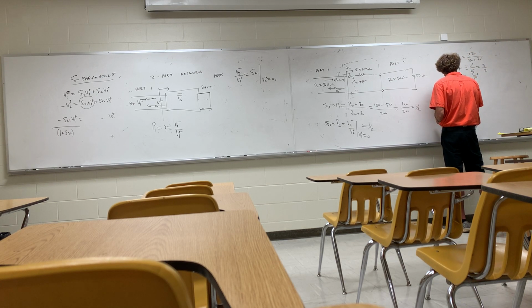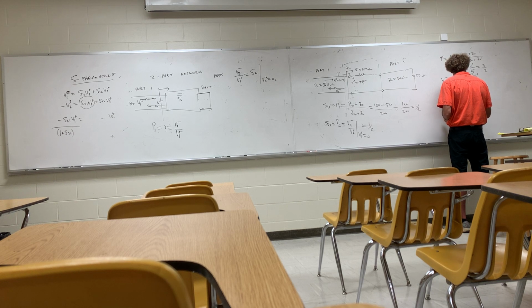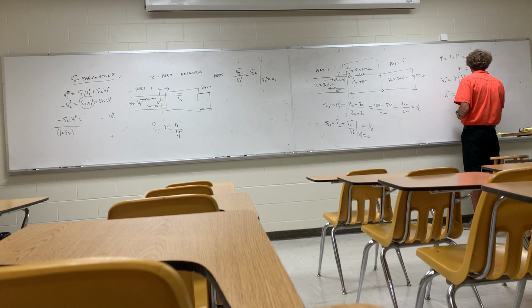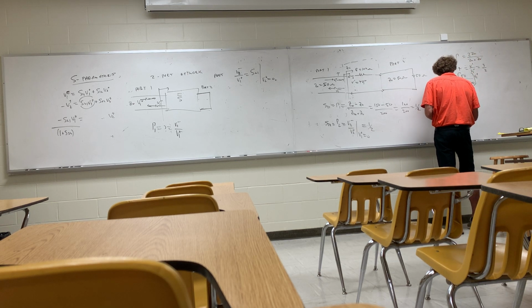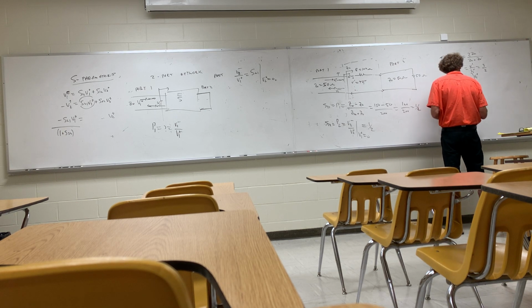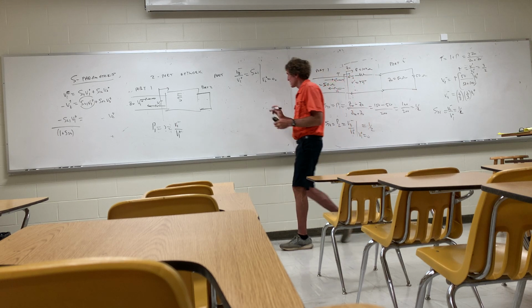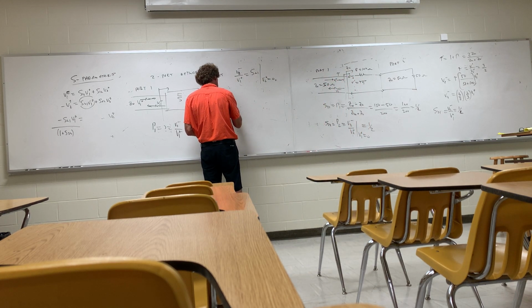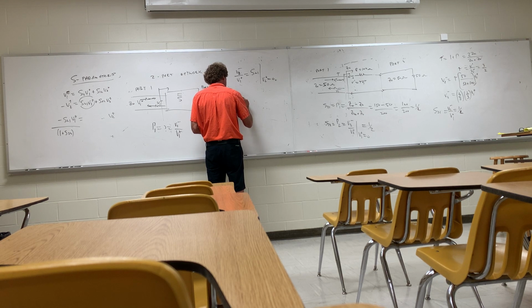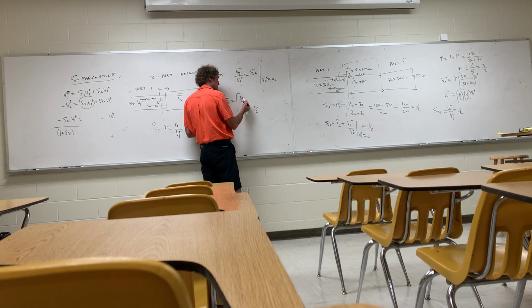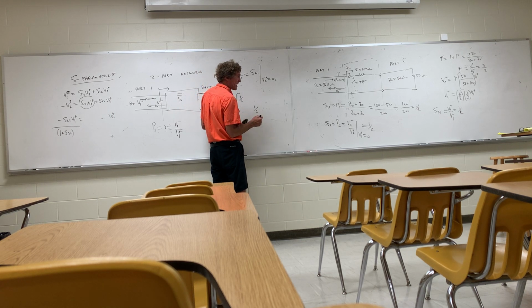So I get V2 minus equal to tau, which is 3/2, times 1/3 times V1 plus, and therefore I can say that V2 minus over V1 plus will be equal to simply 1/2, and that would be S21. So let me go on. This would be the matrix so far. The S matrix for this is 1/2, 1/2. Those are the reflection coefficients, S11 and S22. Then for that, the forward gain is 1/2.